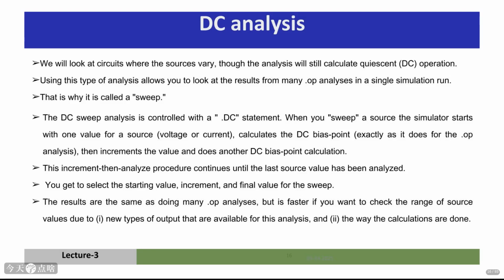Okay, let's talk about DC analysis. This is fundamental. It calculates the steady-state operating point of your circuit, assuming all input signals are constant. But sometimes, you want to see how the circuit behaves as you change a DC source, like sweeping the input voltage. That's where the DC sweep analysis comes in.